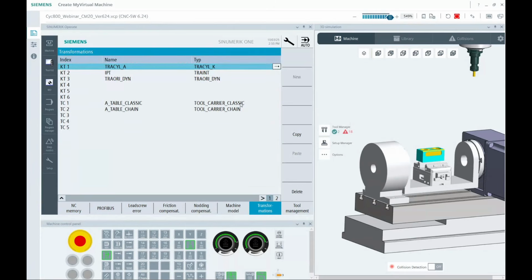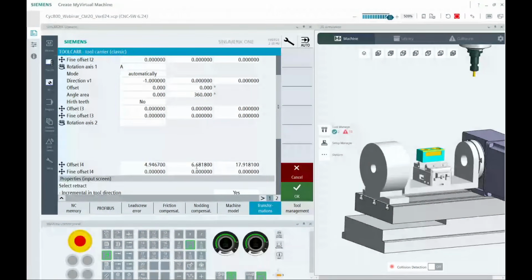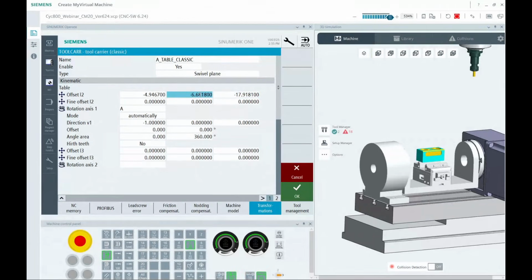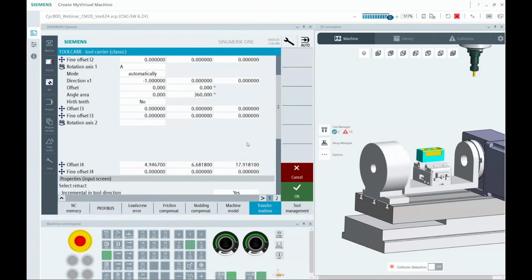and now in this case, you see these two. So you would have just one or the other. So again, if I open up the classic, these two numbers are my critical numbers. This defines the center line in Y, and that defines the center line in Z. And then usually what you would see then, we would close, what they call closing the vector. So I would use the inverse, right? That's a negative. This is a positive, same exact number. This is a negative, that's a positive, same exact number to take the vector, we refer to as a vector, and then look it back on itself.